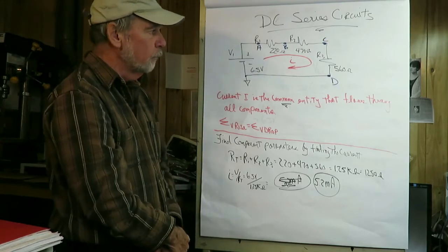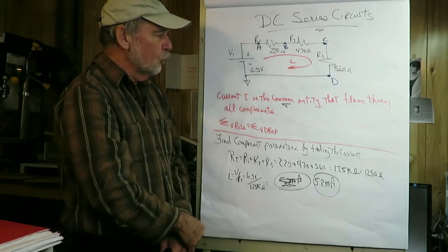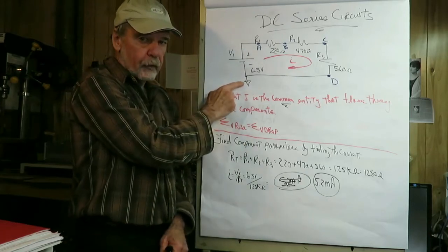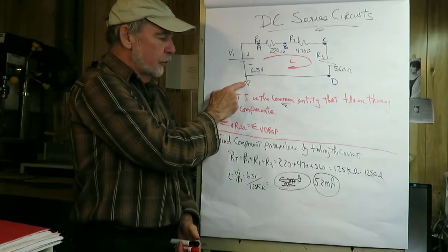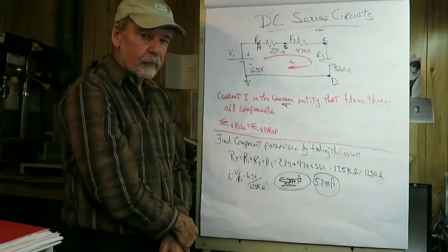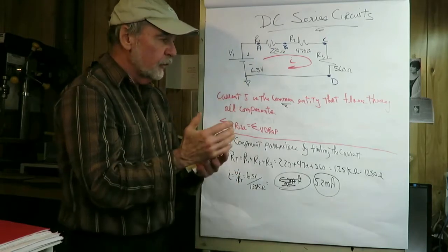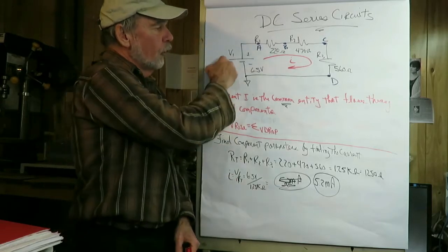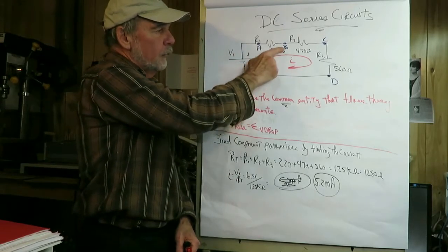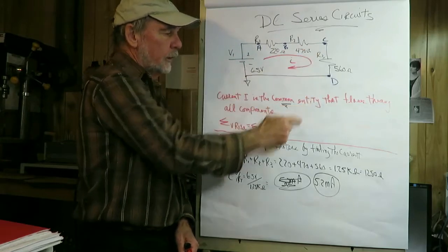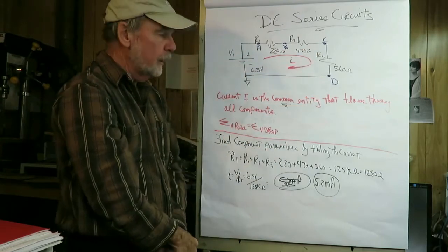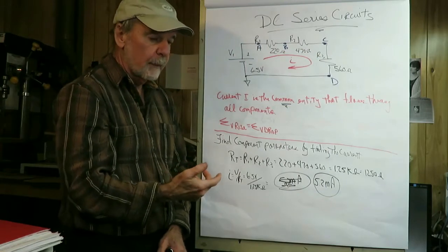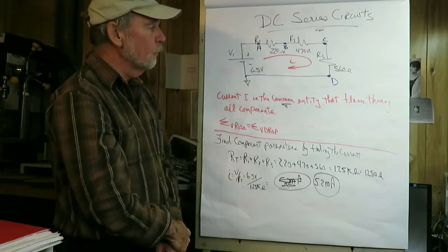very, very important. So if we're looking at this, what we see is we have a 6.5 volt battery and a ground reference here, and the ground reference on your car is basically the chassis. So it's a common point that you reference when you're measuring voltages. As the current flows through here, we have node A, node B, and node C, and node D, which is ground, and we're going to be referring to these nodes when we talk about the voltage drop across specific parts.